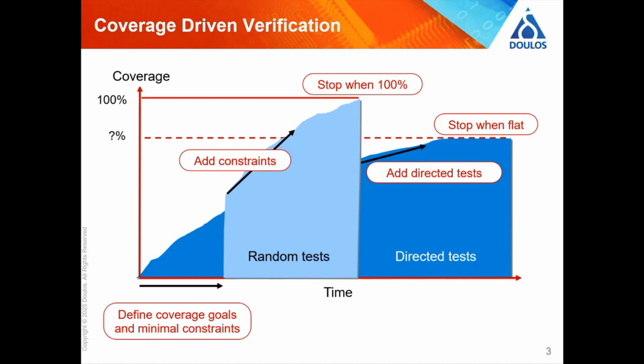Because if we're in the situation where we've got kind of 70, 80% coverage, assuming you've got a way of measuring coverage at all, which is also something we're going to talk about, how do we actually think through what do I need to do to make a test, to test the stuff that hasn't yet been tested? And that's quite difficult to do. So again, quite a well-proven solution to that problem is to use constrained random stimulus generation.